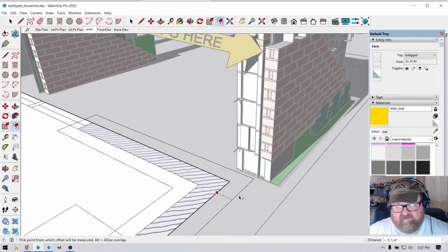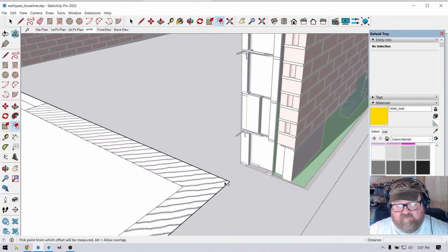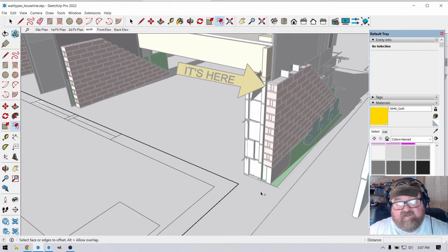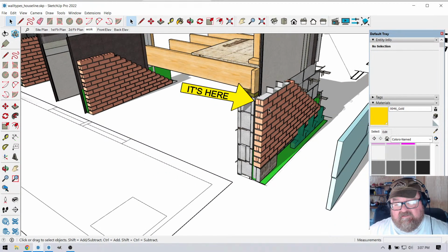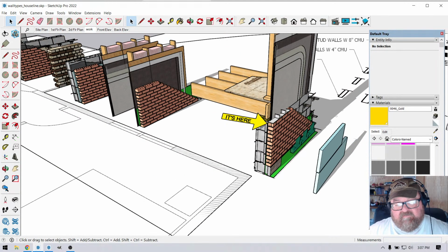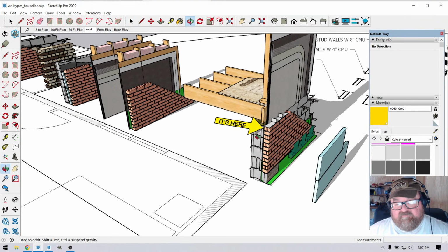He would actually be surveying that point right there because he can't access that point. So what we do is when we're laying this point out on the footings, we allow for the brick, but we don't call that the house line. And I think the more you get into this, the more you'll realize why this is important.